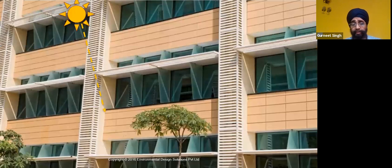Again, this is the Infosys building, the detail of that facade, where they first recessed the window. So it already gave them some shading, and then they added another shade onto that, a horizontal shade. This horizontal shade was done to protect the window from the sun around 10 a.m. till 3 p.m. And actually, you can see the shadow on this column, right? So this is shaded, and vertical elements were introduced to block the early morning sun and the evening sun.